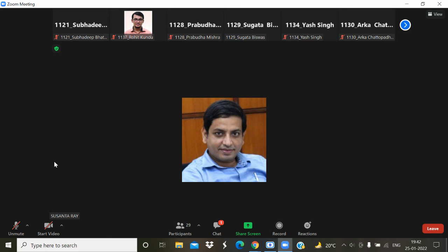L by tau, assume a value between 1 to 3, and instead of tau you write pi D by P. From that you will have a ratio L by D. D square L you have already obtained, and now from this expression you will have L by D. From these two expressions you can calculate L and D.